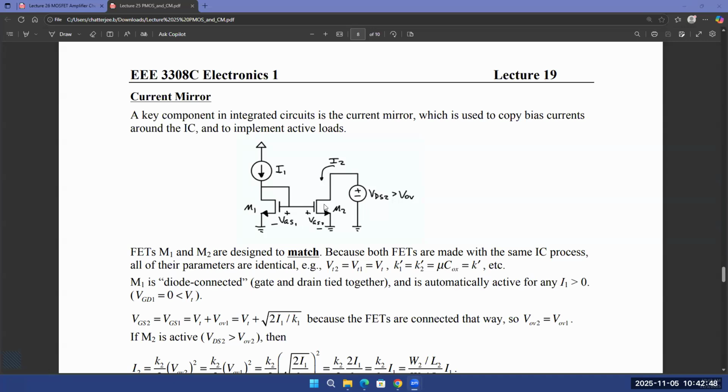You can always use 3 different DC current sources in an actual circuit when you're testing it out in the lab, but that's kind of cumbersome. It's a complex setup. You need to make sure that all 3 current sources have the exact values that you want. There could be variations, there could be mismatch. If you want to avoid all of that, you probably want to create those current sources inside your circuit, and it is possible to do so.